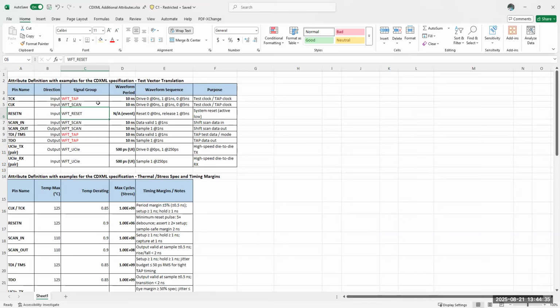People sometimes merge the TCK and the scan, and that same TCK can go to one of the scan clocks. In some cases, people do not want to merge it, and they want to keep it separate functionally, so both combinations of inputs are valid. Right. Low pin count devices don't have the luxury of having a dedicated scan clock, for example. So they might reuse the TCK.